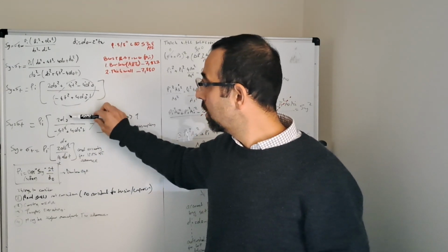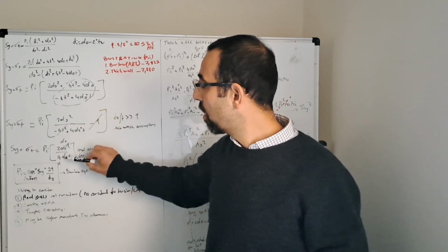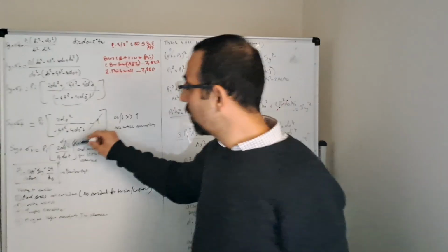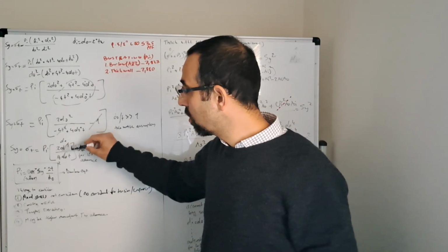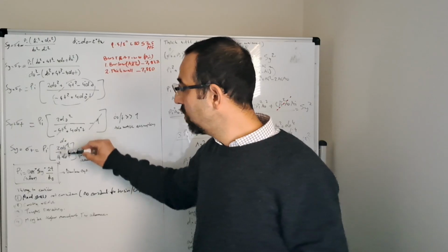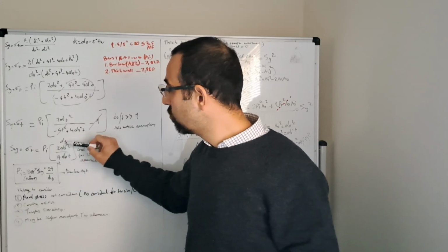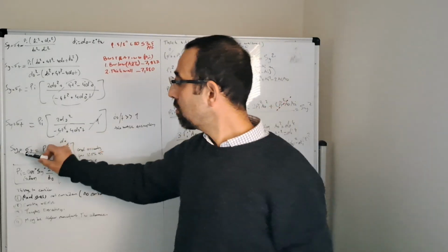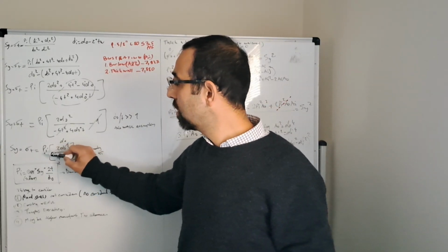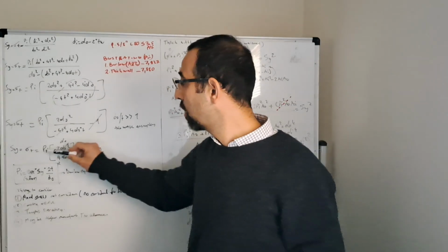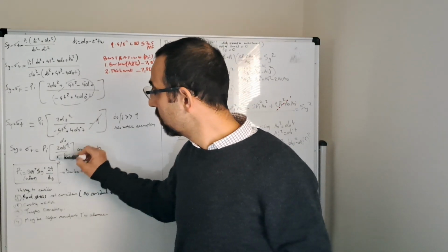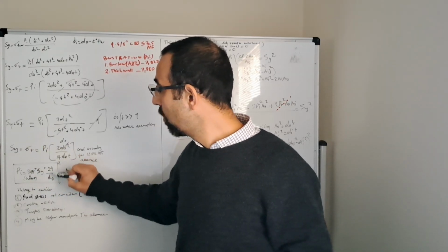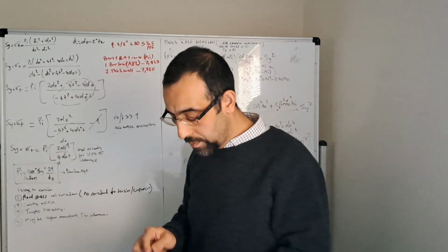Therefore, I'm left with 2 D_O square divided by 4 times D_O times wall thickness. And when you do the cancellations or division, you will come up with D_O over 2t. And then in order to find the internal pressure, which is the burst rating in our case, you will transform this equation into the yield strength times 2 wall thickness divided by the outer diameter.